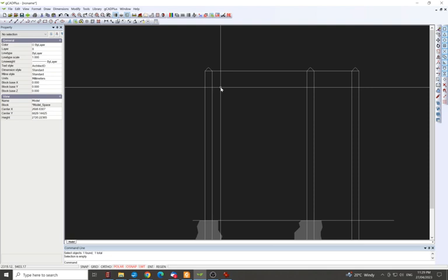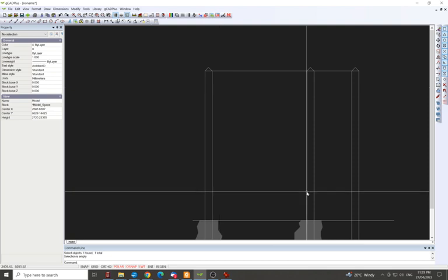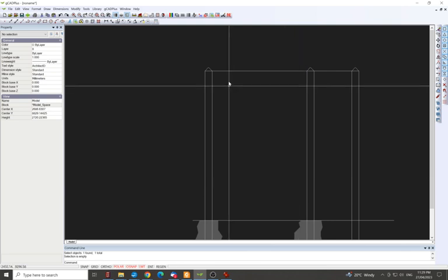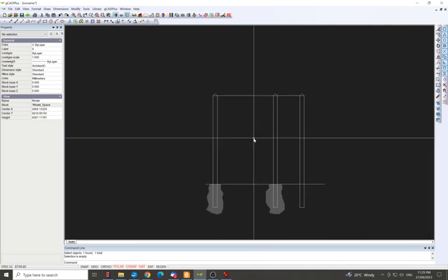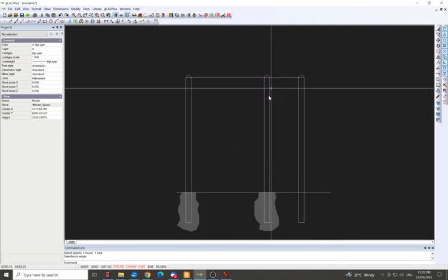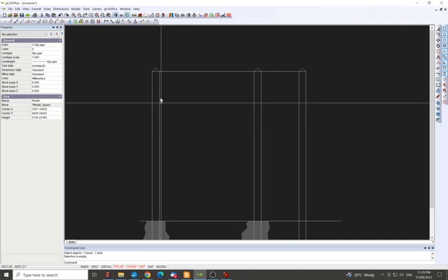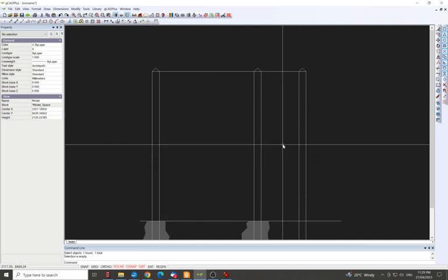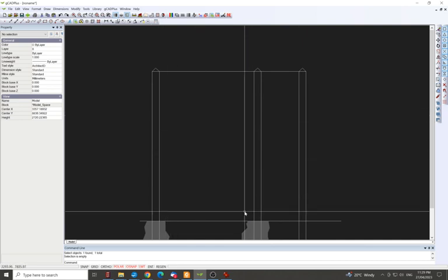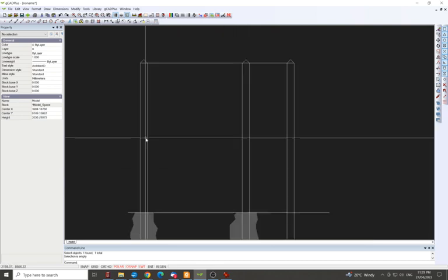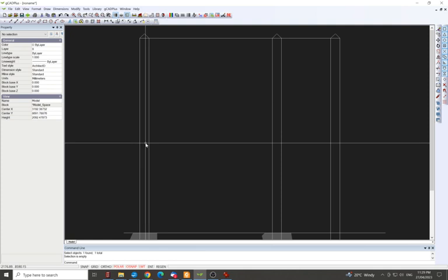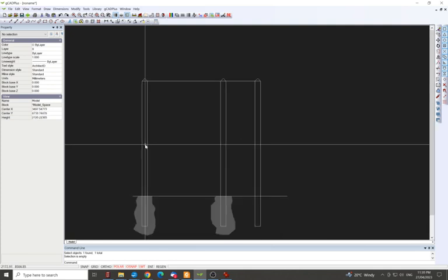So you could just ignore this and just make a frame, draw a frame up. But for the reference of the constructor, it's really important that they know where these posts are, because they've got to know where they've got to weld the hinges on, where they've got to weld the brackets on, where they've got to weld the drop bolt down. Yeah, it's just helpful to know, and what it's mounting to sometimes, because the hinge might have to run a different direction or something.